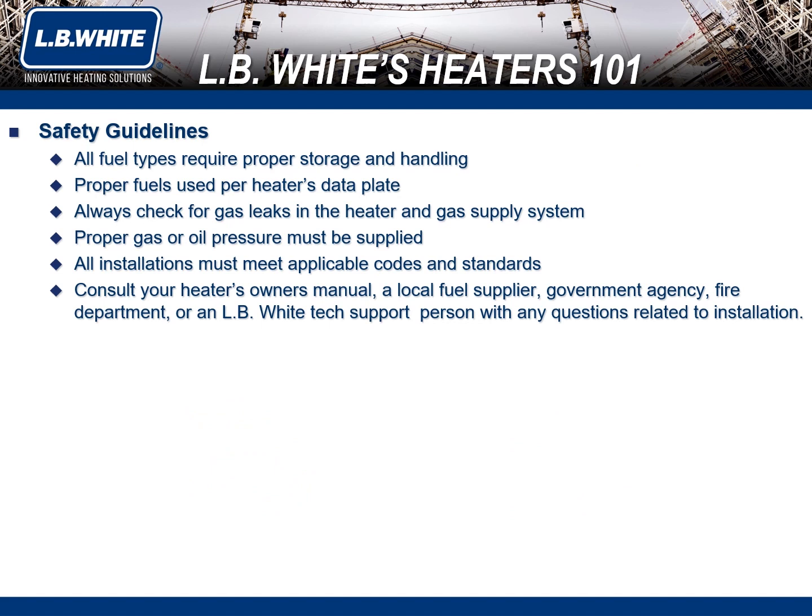Before we come back to regulators, I would like to go over some safety guidelines related to fuel. All fuel types require proper storage and handling. Refer to a heater's data plate for the proper fuel to use. Always check for gas leaks in the heater and gas supply system. Proper oil or gas pressure must be supplied. All installations must meet applicable codes and standards, which may differ by region. And consult the heater's owner's manual, a local fuel supplier, a government agency, fire department, or LB White tech support for any questions related to installation.